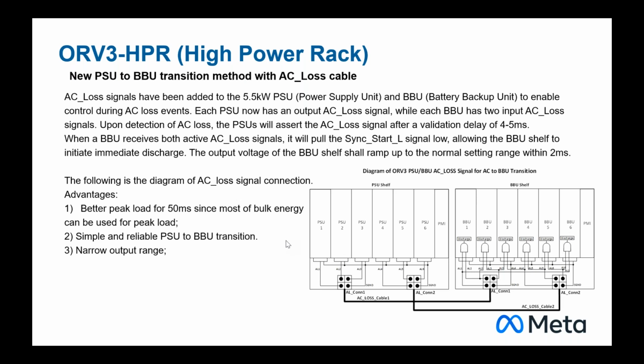So what's the benefit of this change? In the original design, we need to reserve pretty much 50% of the bulk cap energy for the transition during the hold up time from PSU to BBU. In the new design, you can almost fully utilize the bulk cap energy for the peak load.